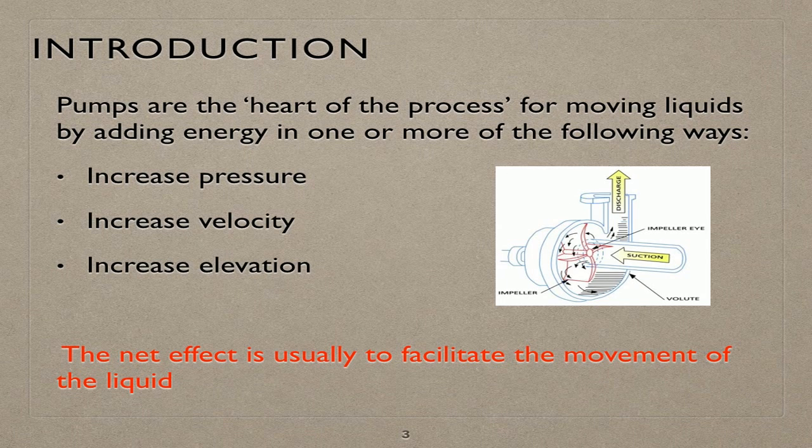Flow movers are the heart of the process, and the pump, which is one of those, is used for moving liquids by adding energy to the fluid in one or more of the following ways: by increasing pressure, velocity, or elevation. The net result is to facilitate the movement of fluids from one point to another point with higher pressure.